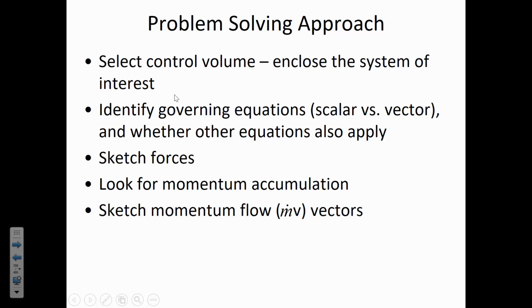Well, you can combine that momentum aspect of the problem with a Bernoulli's aspect where, in order to calculate the velocity of this jet, we need Bernoulli's equation, remember: P1 over gamma plus Z1 plus V1 squared over 2g is equal to P2 over gamma plus Z2 plus V2 squared over 2g.